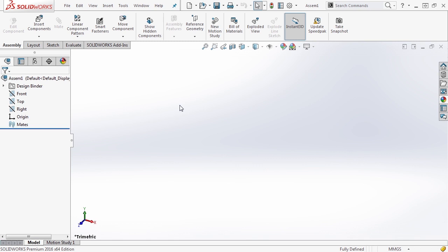There's also great things that come along inside the assembly environment, like bill of materials. Now, when we did our example on creating weldments, sheet metal weldments, and creating those types of files, you have what's called a detailed cut list. And you have multiple solid bodies in those part files, and you will get a table in a drawing, which again, we'll talk about later. But when you have assemblies, you get bill of materials. That means a detailed list of all the components, multiple components, any custom properties you want to send along with that. A very nice functionality inside the assembly environment.